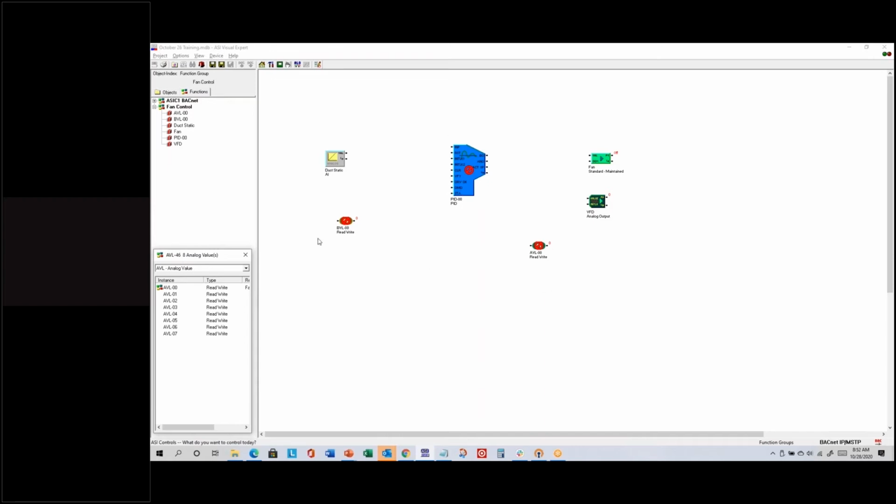Okay, so you can see that some of the icons have the red circle with a slash, so we want to enable those. You could go to each one individually and do a right-click Enable. What I tend to do is select a group of them and enable them all together. There are different ways to do multi-select. The way I usually do it is to just draw a rectangle around all of the ones I want. If you select one that's already enabled, that's okay. Once you have multiple icons selected, you can right-click on any one of the icons and select Enable, and they all become enabled.